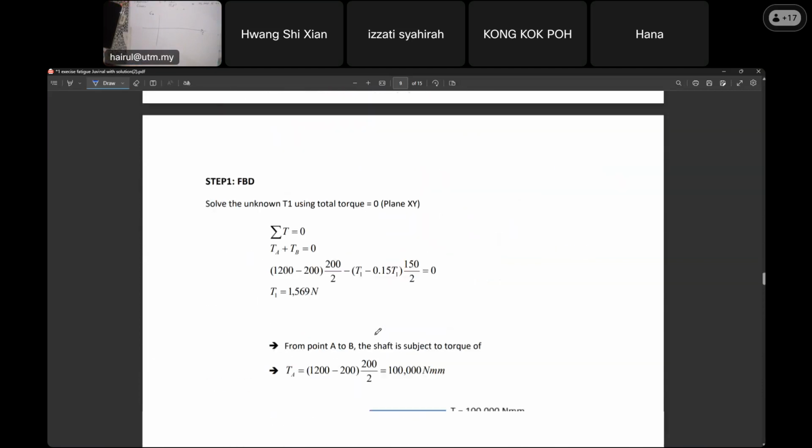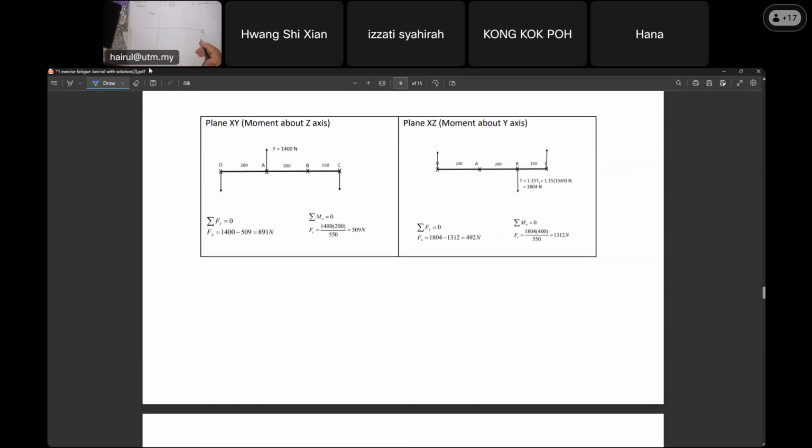How do we plot the bending stress against time, class? Sine wave, yes. What does the sine wave look like for bending stress? Is it like this, above, or on the negative side, or is it completely reversed, positive and negative with the same value and the mean is 0? Which one? A, B, or C? Quickly, for bending. C.